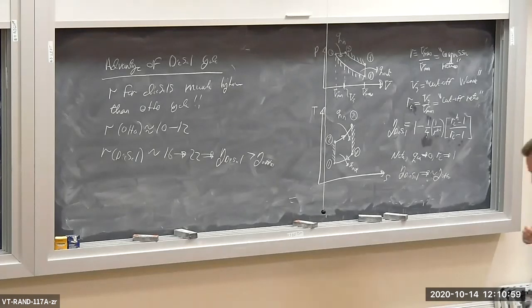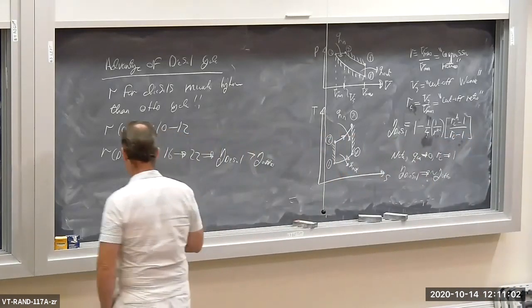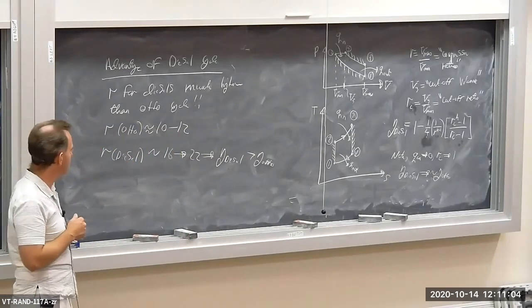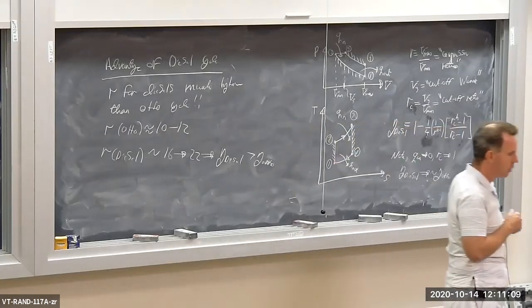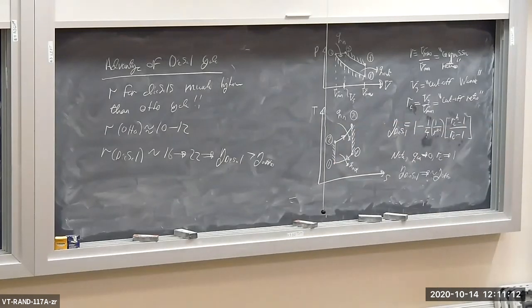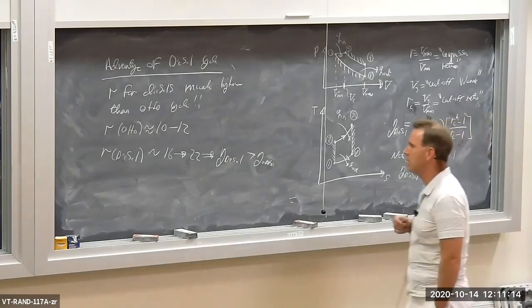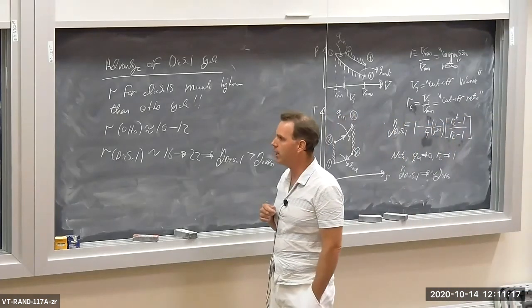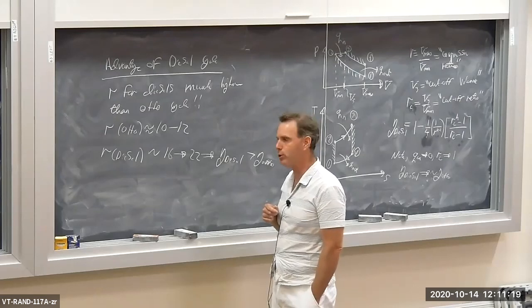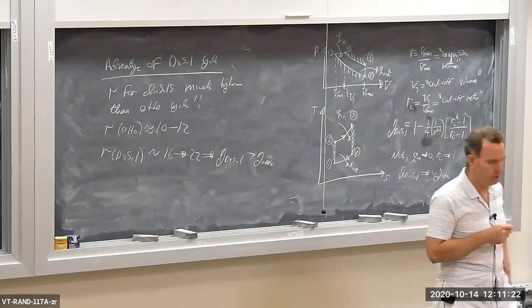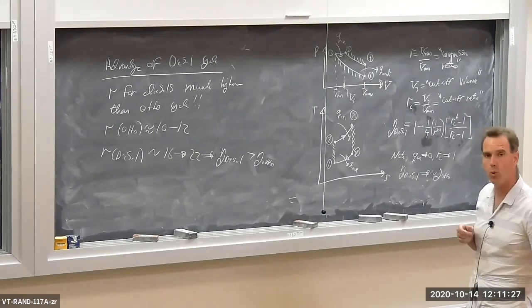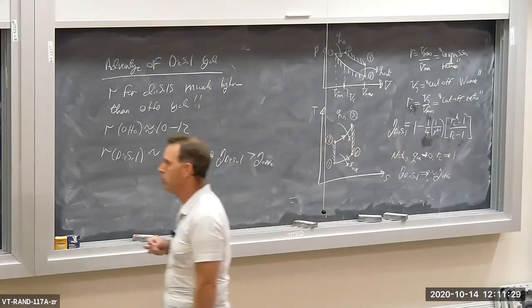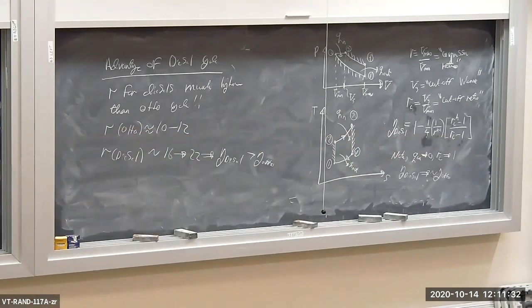Those numbers are going up with recent technological advances and the use of direct injection in gasoline engines as well. Gasoline engines are typically now going towards the diesel cycle, even though they use gasoline. And they're able to do that because they can inject. They're developing high pressure pumps and high pressure systems for injecting gasoline. So gasoline engines are actually going more towards the diesel cycle with the use of high pressure direct injection for gasoline engines now as well, okay?